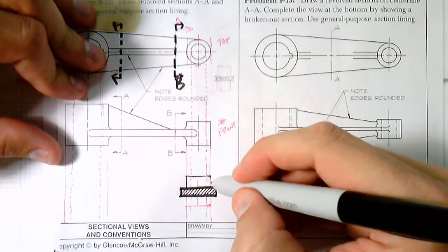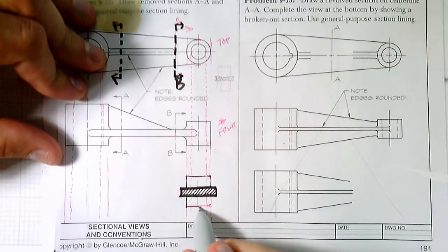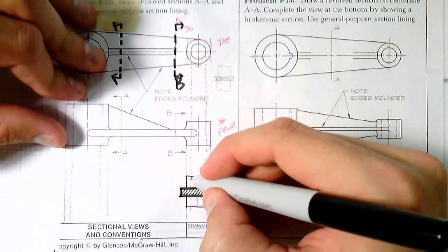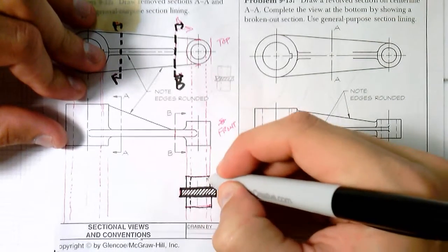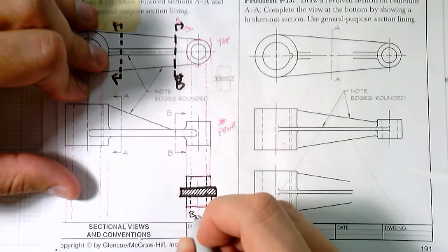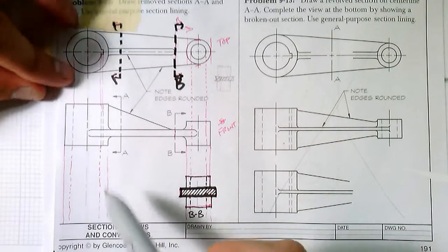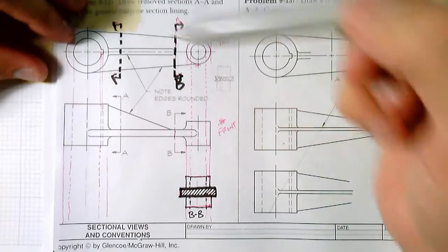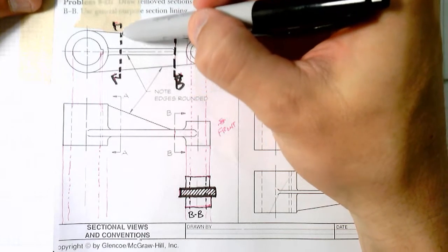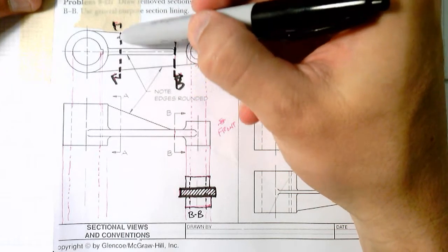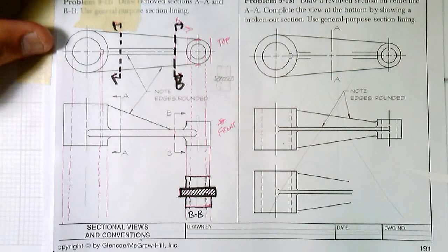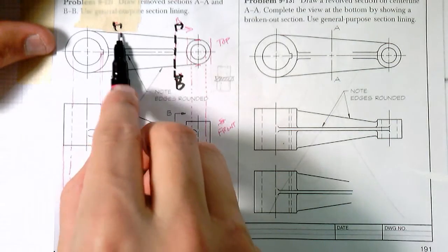And this is just sketching neatly, trying to use some of the same proportion. And so when you look at the cylinder, we'd have our hidden lines that represent the hole through the cylinder. And that's our section BB. Right now, section AA is going to be similar, except one thing we need to look at is when we're cutting through AA and we're pointing in that direction, the area we're cutting right here is slightly smaller than the cylinder. Right? So in other words, if we take the length of the cut area, which kind of goes to